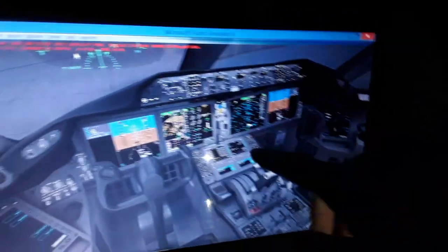The flight management computer is going to calculate the trim position. Use also the flight control computers, the autopilot flight director system panel, and auto throttle. And we're gonna have automatic trim from takeoff, climb to cruise, and approach and landing. If we need, we can use the manual trim switch to trim the horizontal tail of the aircraft manually. Also the flight management computer, as we fly, the aircraft burns fuel, so it will shift the center of gravity during flight. This is also recalculated during flight.